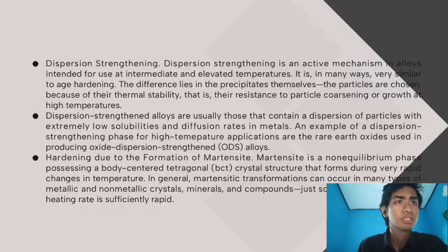Cobalt silicide particles in copper alloy C63800, for example, provide fine grain control and dispersion hardening to give this alloy high strength with reasonably good formability.